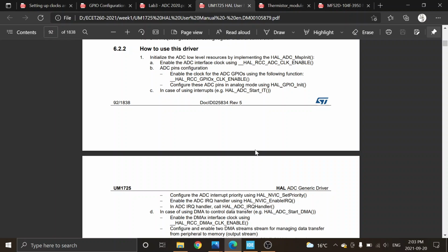The graphical interface, as soon as you select the pin you want and say it's an ADC on ADC3, sets all that stuff up for you. Okay, generates a bunch of the code. You can go look at it. It's doing all of this stuff. It's going to call HAL ADC MSP init and do a bunch of initialization and say, there's an ADC set up. You said it was 12-bit. It's 12-bit. I don't know what you want to do with it. Won't do anything else. Okay, but it'll initialize it. And then we need to scroll on down a little bit.